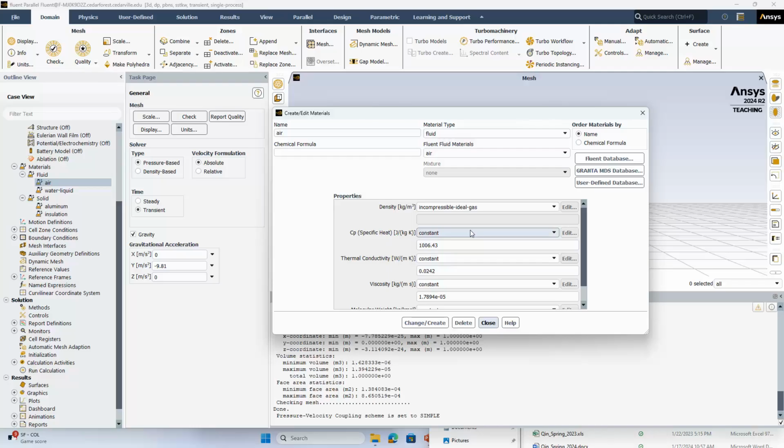There is a fixed pressure, which in fact is very close to our real situation, right? The air pressure inside the cooler is maintained roughly constant. At least this is our goal, to maintain a constant pressure. So here the pressure is constant, so the air density, which equals pressure divided by RT, now only depends on temperature. When temperature increases, density drops. When temperature drops, density increases. So this is what happens here. Click change, then close.